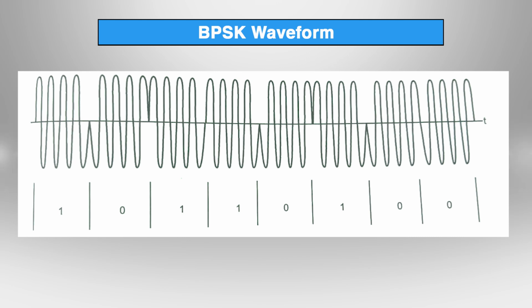We have a PSK waveform, whatever PSK waveform we get from the complete system. So, what is exactly happening at bit 1 and what is exactly happening at bit 0? Definitely, you can see from this system or cycle, whatever sinusoidal we are applying here. Whenever there is a change in a bit, the phase changes by 180 degrees, right. You can see here the first bit has the complete carrier, and just changing the bit to 0, the phase changes by 180 degrees. Even with a second signal, that is 1 1, you will find there is no change in the carrier wave. Once you get a change in a bit, you will find a change in phase. So, this can be seen from figure number 5, right. So, this is about the PSK waveform.